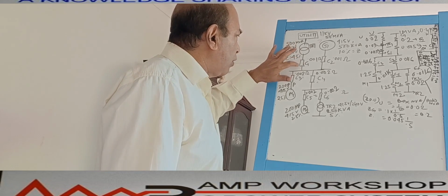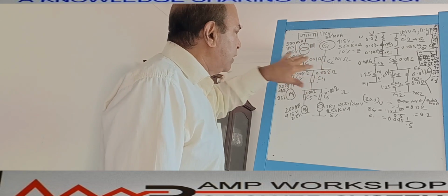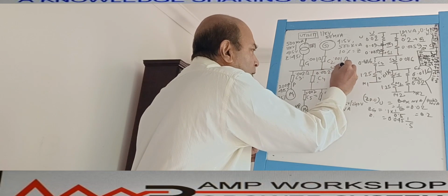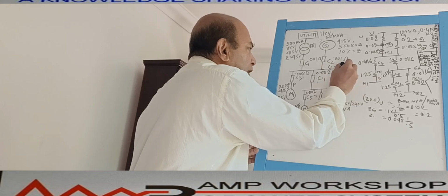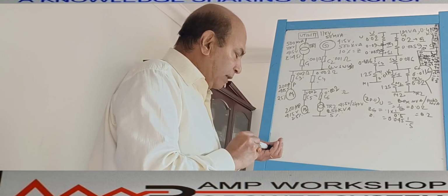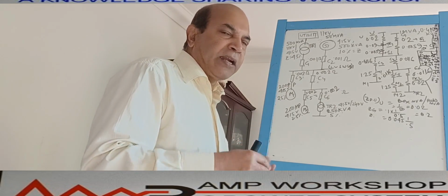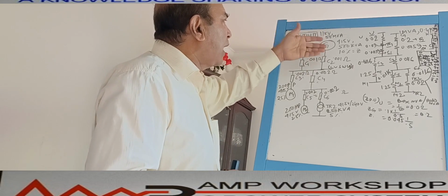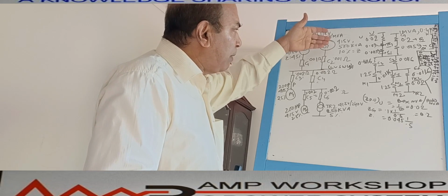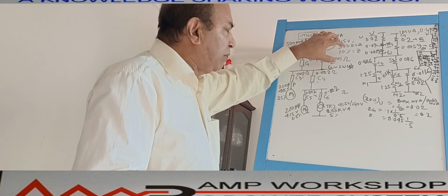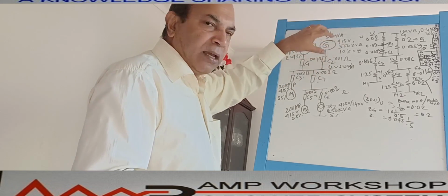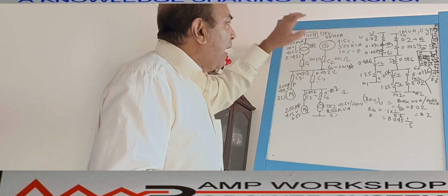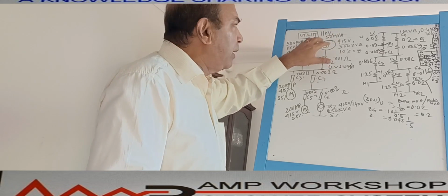Then through a cable, it is connected to the low voltage switchgear. You can say LV switchgear 1. That is the first switchgear from where it is connected. As this is utility power, it can switch off at any time, as I said before, so there should be an emergency power supply arrangement, or it can run in parallel with the utility. That generating unit is installed by the owner in his own plant. It has not come from the utility, because this generator is used as backup power for the utility, and based on requirement it can run in parallel.